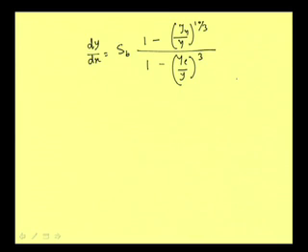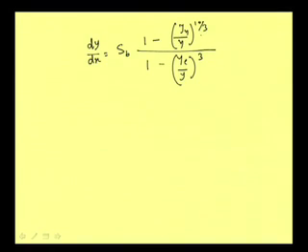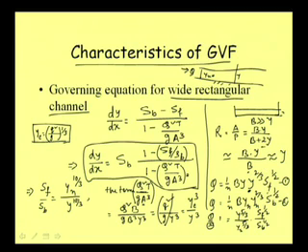Now this expression we are getting by using the uniform flow equation, or the resistance flow formula, as Manning's formula. Now, in place of Manning's formula, if we use Chezy's formula, then again in place of (yn by y) whole to the power 10 by 3, we will be getting (yn by y) whole cube. Let us just see what we can get using Chezy's equation. And of course, earlier we wrote this expression using Manning's formula, using Manning's equation.